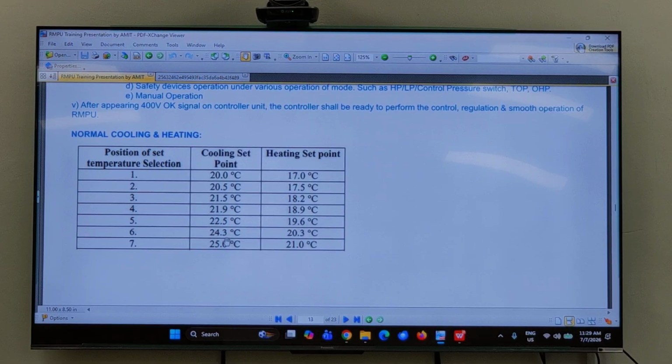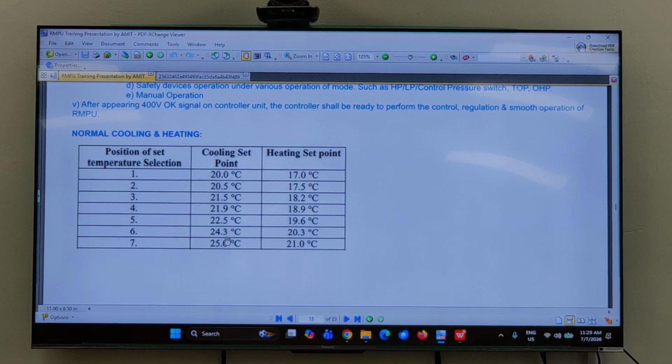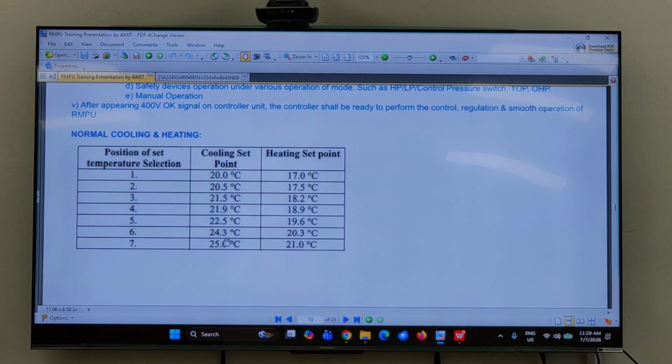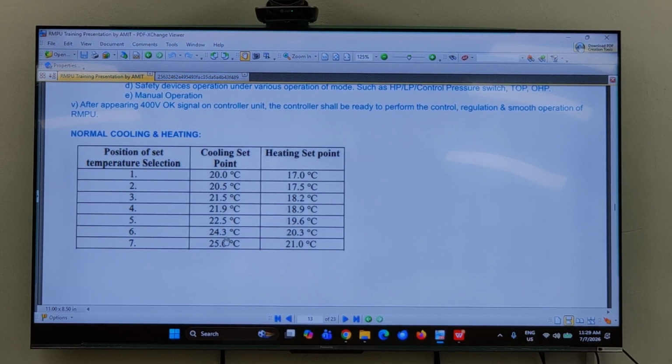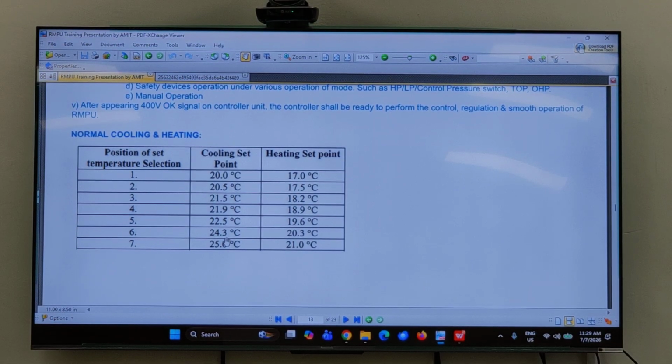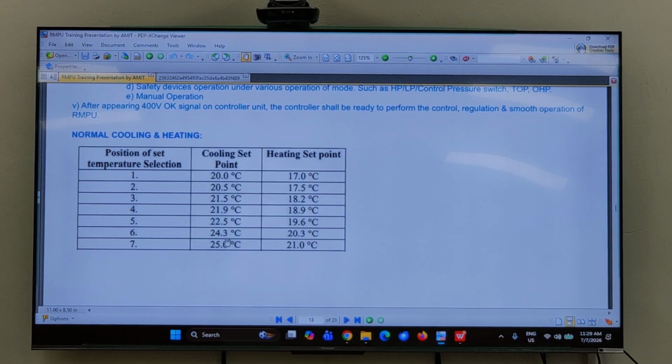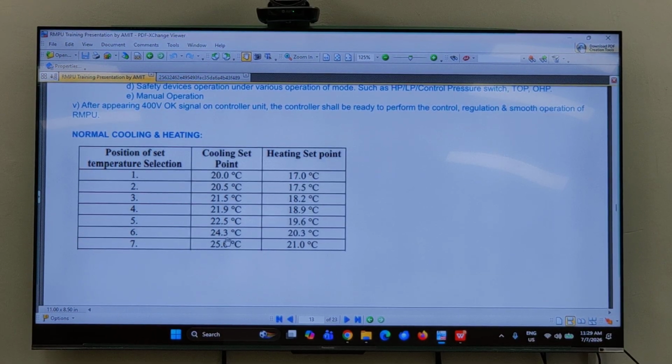If the environment temperature is less and we are putting the set point higher, like suppose we have kept it near about 19 degrees, and the outside temperature is 15 degrees or 12 degrees, in that case cold air is coming, so we cannot go for only the blower. We have to run the heater. So when the heater is on, the air that is coming will heat up and go to the coach. Once it is maintained, the heater will turn off again, and again we go through the same cycle.